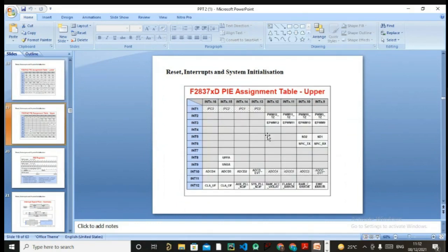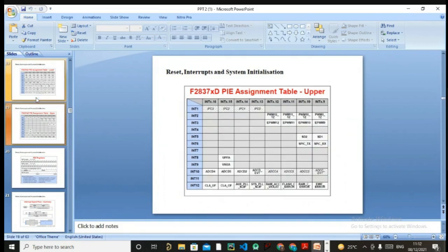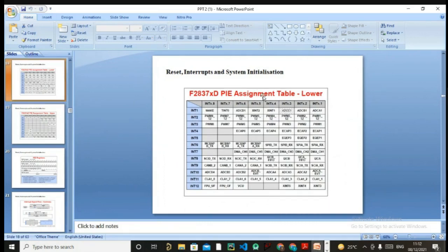Okay, it's not there. It's not listed. So maybe that interrupt is used for servicing your main CPU only, so maybe you don't have access to that particular interrupt. Otherwise, it would have listed timer interrupt 1 or timer interrupt 2. So I guess we can use only timer interrupt 0 for this particular thing. Since there is no other interrupt like timer interrupt 1, you cannot trigger that interrupt and use that interrupt service routine.